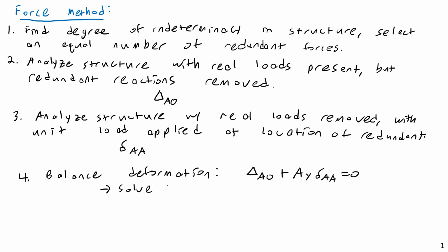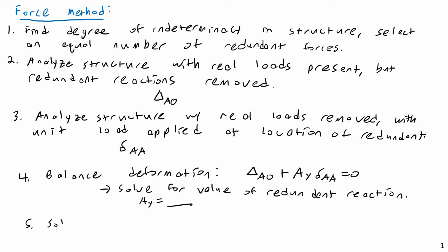Solve for the value of the redundant reaction. So in this case, you'd solve for AY. So you'd have AY equals some number. And then finally, the last step is just to solve or analyze the now statically determinate structure.